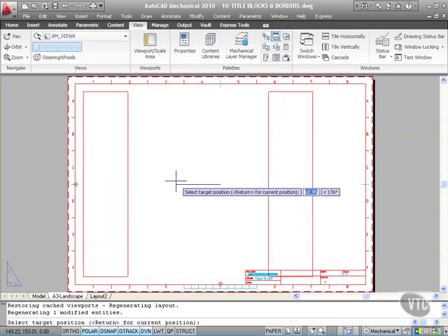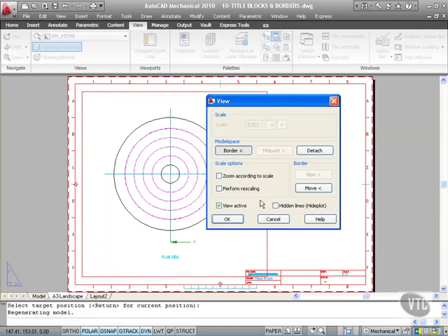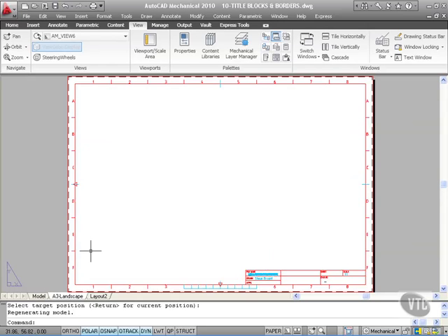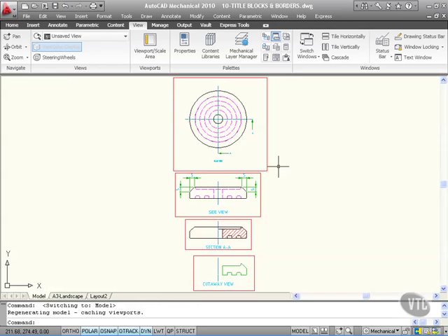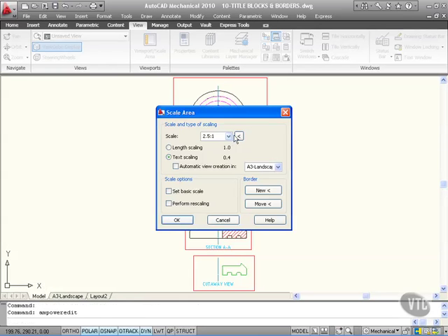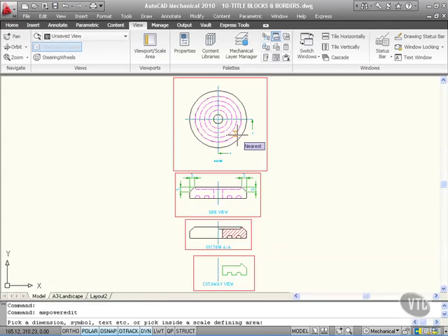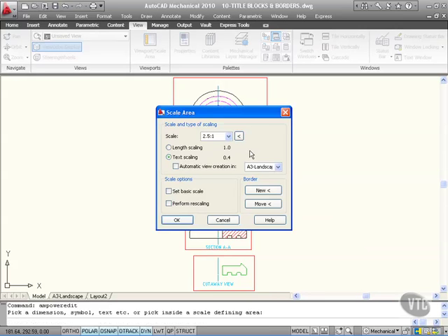It's quite big, you'll notice. Look, if I drop that in there, it's going in at twice its normal size. In fact, 2.5 its normal size there. So what I'm going to do there is I'm going to cancel that. I don't want that to go across. I go back to model here, and what I'll do now is I'll edit this one. So I'll double click on the scale area and say that I want to take that back to the actual 1:1 size that it originally was. Now I can just hit escape there or click inside there and it allows me to edit it. So I say that I want that to be 1:1.